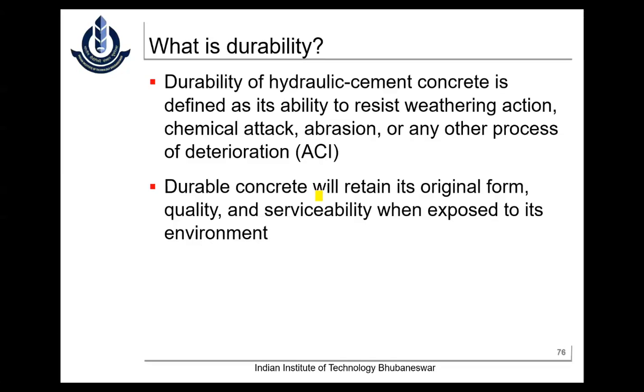See, the meaning of service life and durability is, let's say with OPC cement, your first crack, your first distress, maybe you have noticed after 15 years. When I'm using a durable concrete, it doesn't mean that it will not show any crack. It means that I'm prolonging my service life. Instead of showing the first distress at 15 years, it may show up at 25 years. That is what we're trying to enhance in the service life of durable concrete.